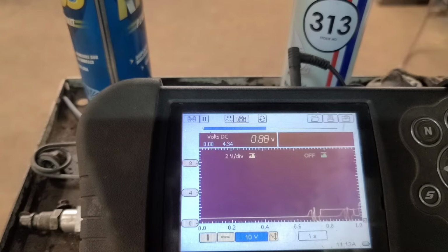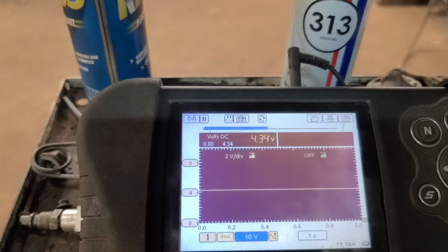And then the third wire, the white-green wire, which is pin C, is a signal. And that's supposed to be duty cycled, or pulse width modulated. And I've got 4.3 volts on there. So either the 5-volt reference is open, this is the 5-volt reference in the middle, and it's 0.66 volts, or the sensor is pulling it shorted to ground.